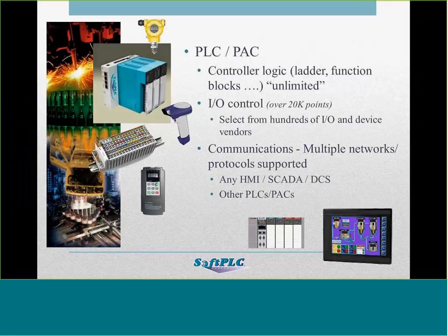So you can connect to any HMI or SCADA system or GCS system via standard protocols like Modbus, Modbus TCP, DF1, other Ethernet protocols, Profibus, all those kind of things. And we also can talk peer-to-peer to other PLCs. So if you've got Modbus devices or Allen Bradley PLCs or other Soft PLCs, they can send messages back and forth. So there's a very rich set of communications as well as a rich set of I/O interfaces.